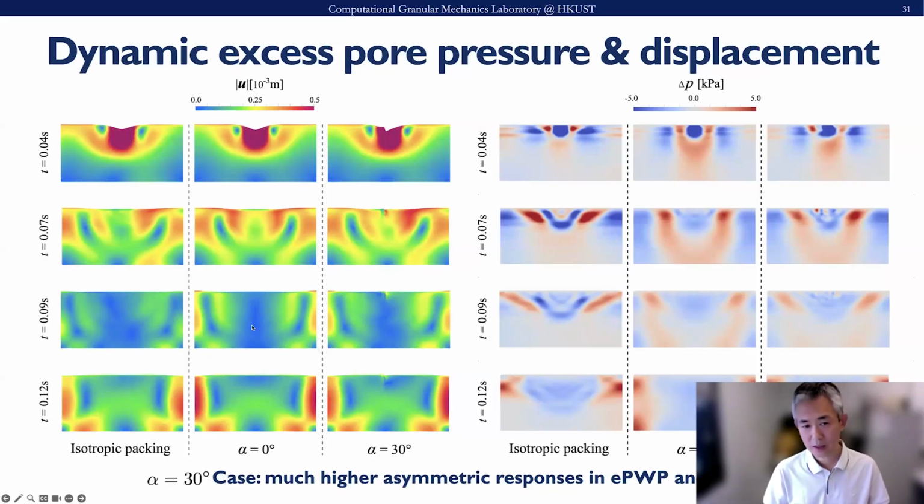We can further make a comparison between this displacement field for the three cases with the excess pore pressure generated during the punching. Again, there's a strong correlation between the excess pore pressure generation and the permanent deformation in each case. But we observed that the excess pore pressure dissipation is not fully synchronized with the deformation patterns. So the two are coupled, but they are not synchronized.